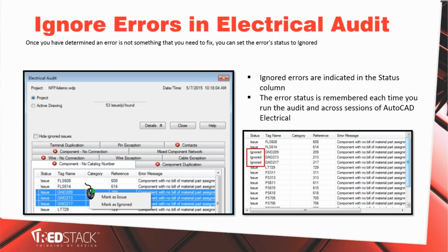And every time you do a report, it will say, oh, you got 200 errors, but in fact, probably only 20 of them are the real errors. All the rest are false alarm. And you couldn't ignore it back in the old days, so kind of annoying. Okay, but nowadays in 2017, you can now ignore those potential false alarms. When you create a report for the first time, all you have to do is select the potential errors, right-click, and choose Mark as Ignored.